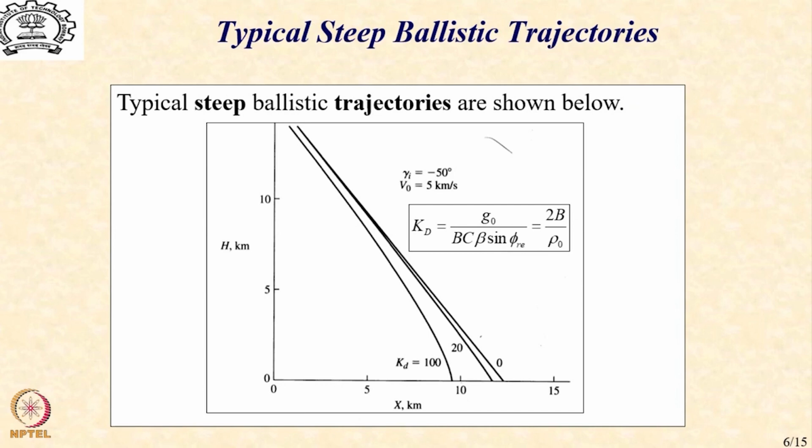And a large value of ballistic coefficient, as we have seen earlier, is directly possible with a small value of drag coefficient or a large weight. Which means that vehicles which are either heavy or have a small drag coefficient or a small frontal area will describe a straight line trajectory, and the equations that we have used will be reasonably applicable to give us the velocity solution.